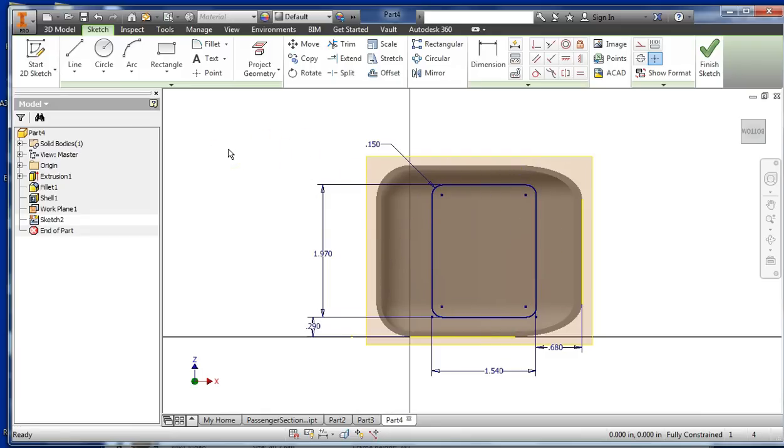Okay, there's a detail B that's been exploded to help us understand the dimension of those, and it is a rectangle that looks like it is 0.04 in width, at least in the detail the way they show it. So it protrudes off of that rectangle by 0.04. I'm seeing the 0.09 and taking away the 0.05 thickness of this piece. So that little thing is going to be 0.04, and then off to the side I can see that in parallel to the side it's got a distance of 0.05.